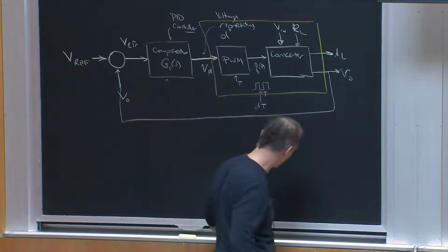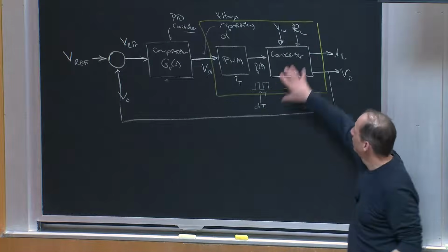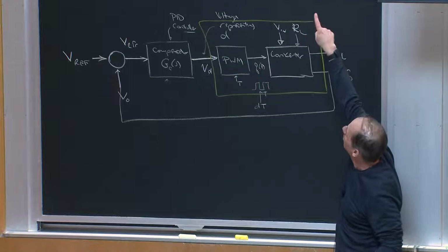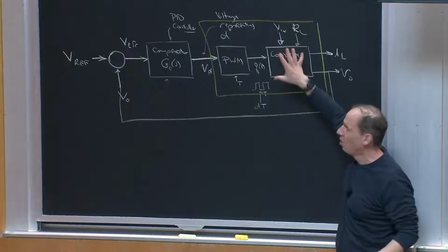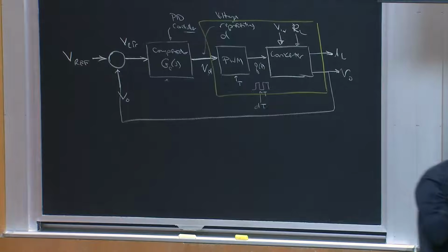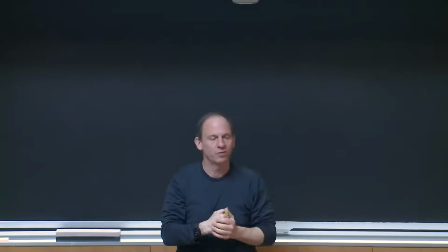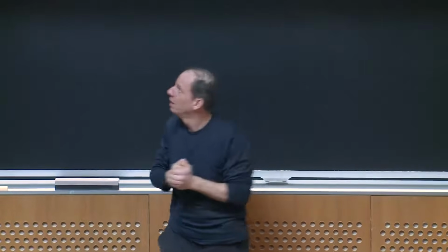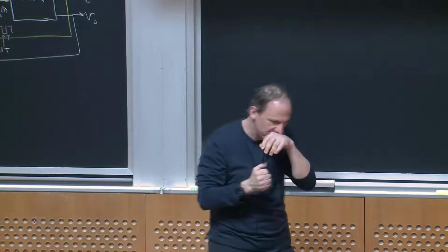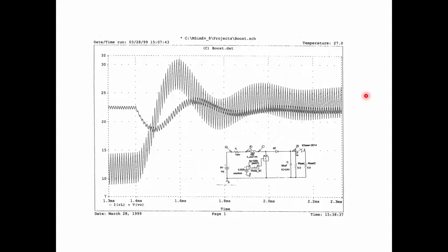And so what I'd like to talk about is how do we build this model, this dynamic model, instead of a periodic steady state model. What does the dynamic model of this thing look like? Okay, from variations in duty ratio, for example, to the variations in the output voltage, okay? And coming back to this picture, right? We can see that what we have here is a bunch of switching. Here's the switching ripple, the triangular ripple current in the inductor. And it goes through some oscillations, and then it settles down. And the same thing with the capacitor voltage.